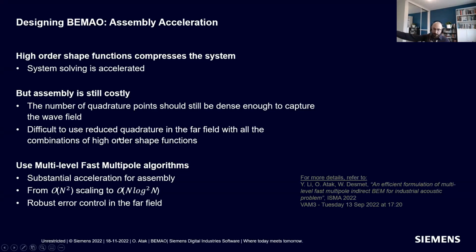The typical setting was, I guess, 5 elements later, instead of using 4 Gauss points for a triangle, you would use a single point. This has worked quite well over the years. Of course, there were some scenarios where you had to increase the quadrature, and it's an approximation, but because it's in the far field, it was working.